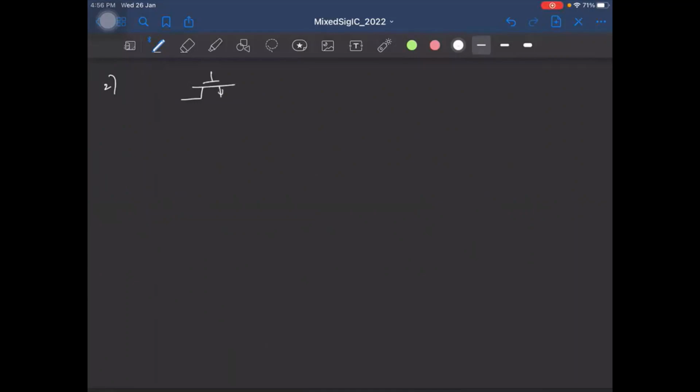So we'll note now that the NMOS switch acts like a good switch for low Vin, and it cannot be used as a switch for higher values of Vin, right? So obviously we expect that there should be some dual device that will do the opposite job. That is, it will be a good switch for high Vin, but a bad switch for low Vin. Okay. So I'll just put a tick for NMOS. Right? And that dual device is what? It is the PMOS, right?